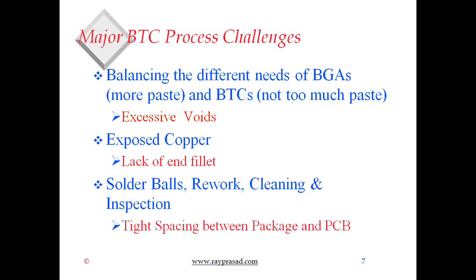And then the issues about solder balls, rework, cleaning, and inspection always add a challenge, because we have very tight spacing between the package and the board. Those issues are there for other components, but they become more of a problem, especially the cleaning and inspection.